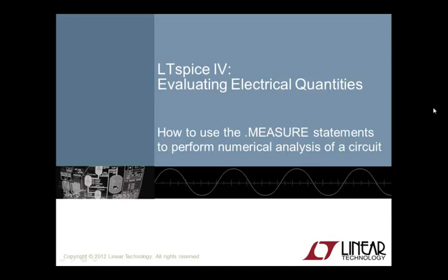Utilizing LTspice IV waveform viewer to analyze a circuit and perform basic measurements is very useful. However, there are times when you need to evaluate a circuit with a numerical analysis. For these circumstances, .measure statements can be very powerful in evaluating user-defined electrical quantities.